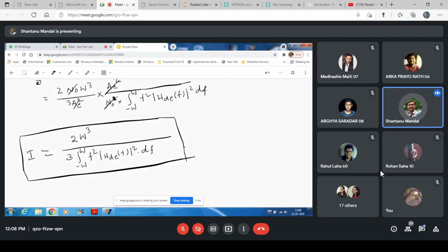So to minimize this distortion, we have to use the de-emphasis filter at the receiver, and the filter which is the reverse of the de-emphasis filter is used in the transmitter section. That is known as the pre-emphasis filter. So the pre-emphasis filter and de-emphasis filter are nothing but filters which can artificially boost up the message signal amplitude at high frequency.